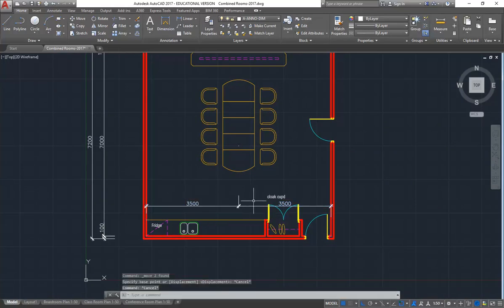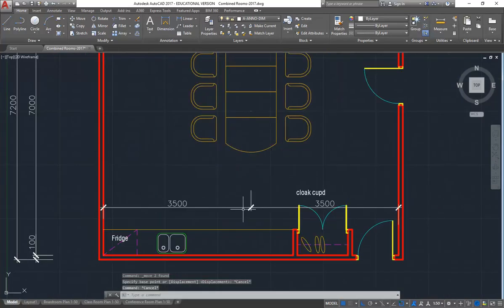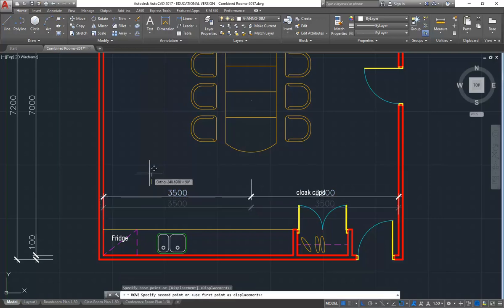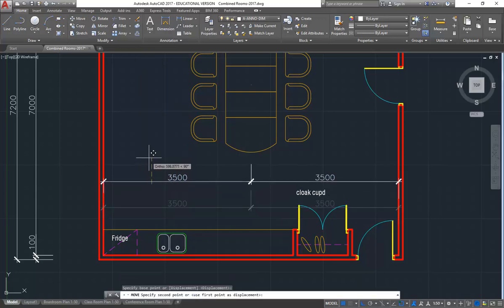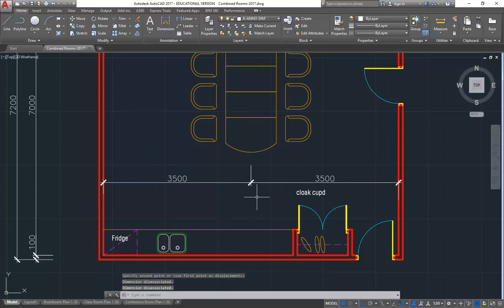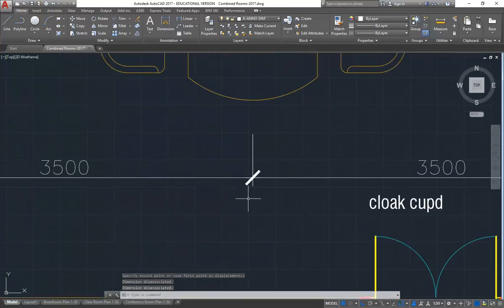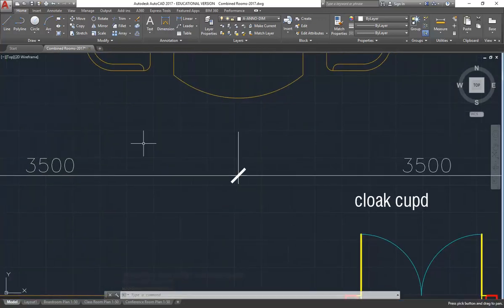Now notice here I'm using the move command, so you can use any of the other commands you've been using on dimensions as well. So if I select those 2 dimensions, then I can click the move button and bring them both up. And then to do the centre line, again there is a centre line symbol and there are a few tools that'll do that automatically, but here it's probably easiest just to make some text.